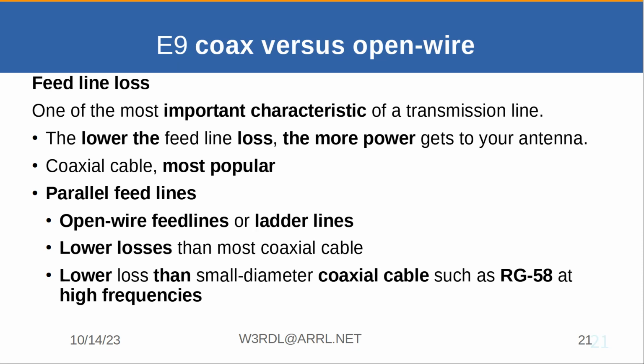I don't know. Where's the highest current? Isn't that at the base, right at the feed point? Well, for a dipole, the highest current is at the center. Which is why you feed them in the center for the lowest impedance, because impedance is just the ratio of the voltage to the current. So the voltage is zero and the current is maximum.